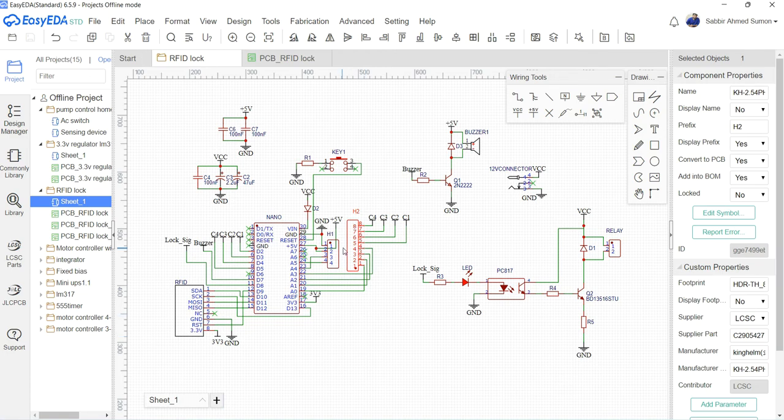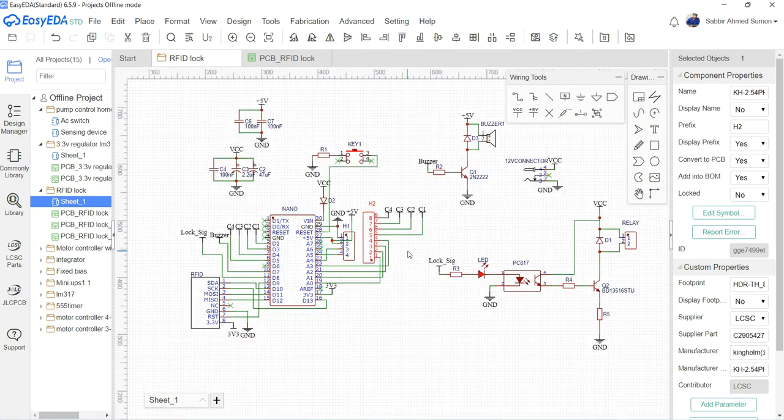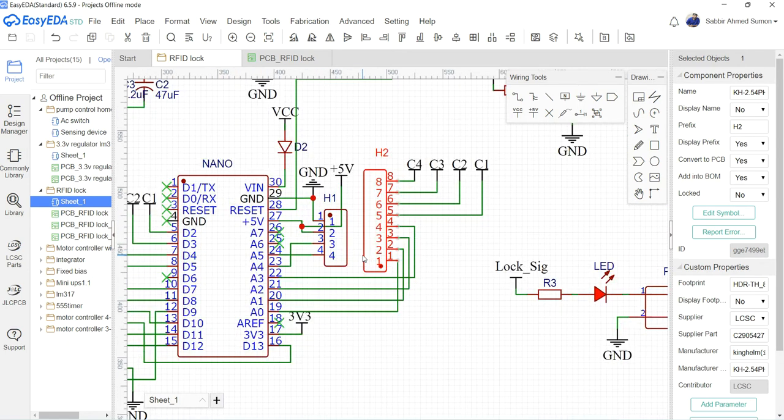And this is the connection for the keypad. This is the connection for a 4 into 4 matrix keypad. We can also use a 4 into 3 matrix keypad with this connection, and we just have to ignore this connection, or just do nothing for this connection. And look, the analog 0 pin is connected across the row 1 pin of the keypad.